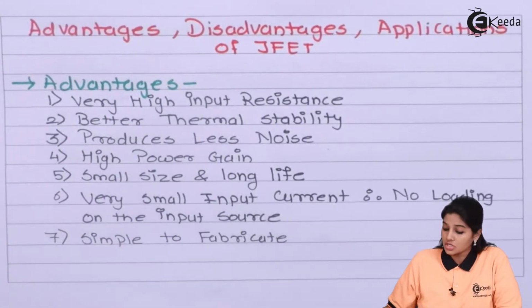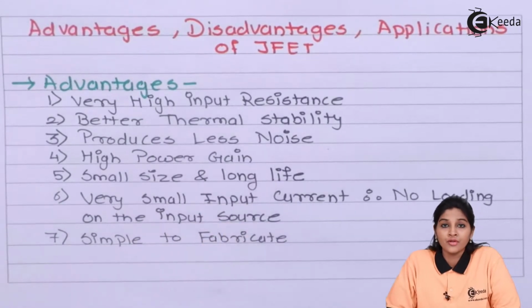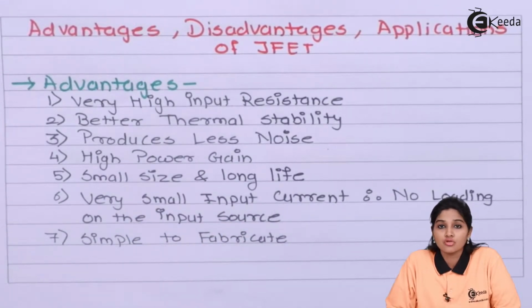The second advantage, it provides a better thermal stability. The JFET has negative temperature coefficient of resistance. That means as the temperature increases, the current decreases. And because of that, the JFET has better thermal stability as compared to bipolar junction transistor.